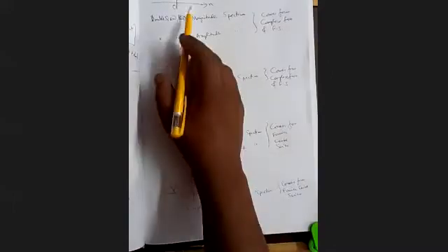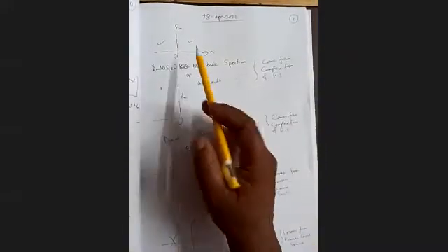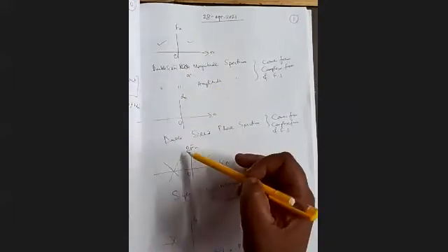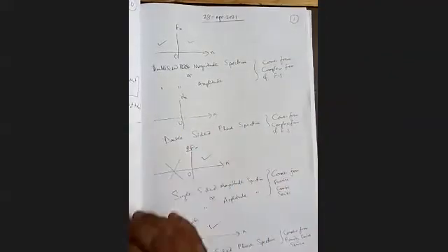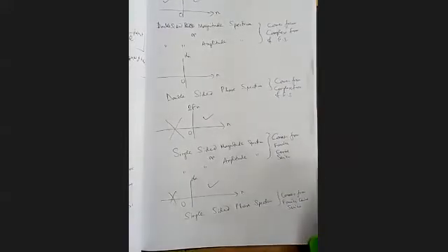So from double-sided we can get the single-sided. How? For Fn and 2Fn, just a 2 will be multiplied in the magnitude part and the negative part will be removed here. And what about the alpha n? Only the negative part will be removed. That's all, to get the single-sided phase spectrum. So let's see one problem on this particular aspect.